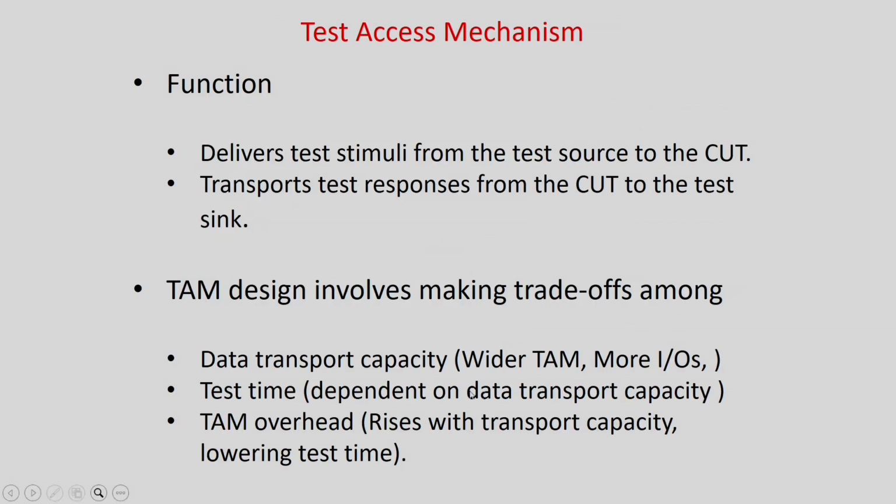Test time depends on the test transport capacity. For test data transport, like test data capacity, there is a wider TAM, more number of IOs, as I told you, which gives a higher access to the chip, but resources will be more. TAM overhead rises with transport capacity, lowering test time.